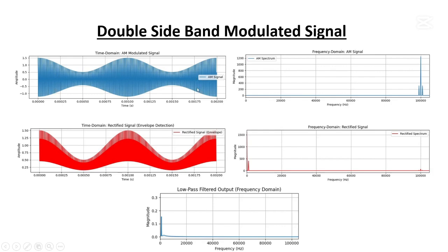You can see that this is a wave, and it can be clearly observed that this is an AC wave because half of it is in the positive domain and half of it is in the negative domain. So this is an AC sinusoidal wave, and after passing this signal through a bridge rectifier, the signal will look like this.